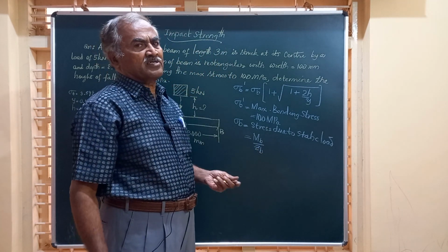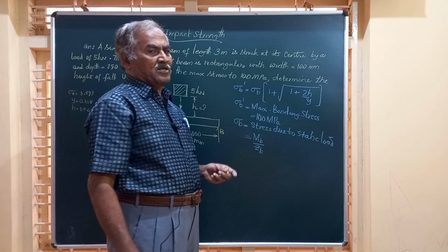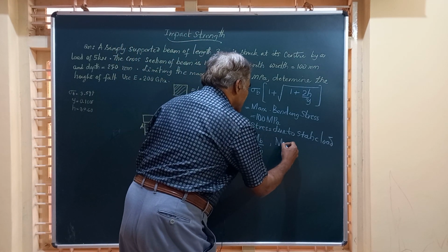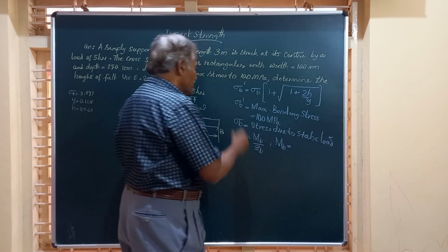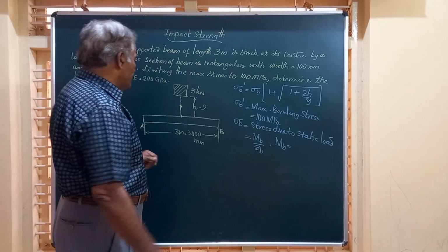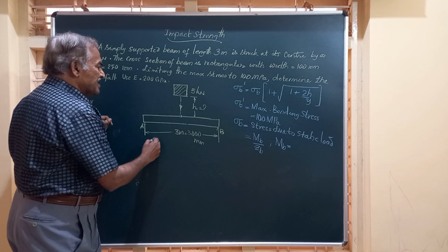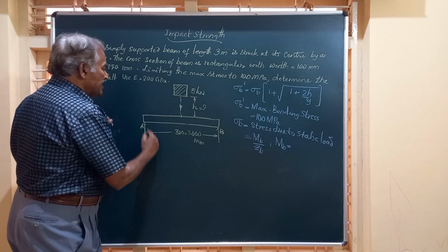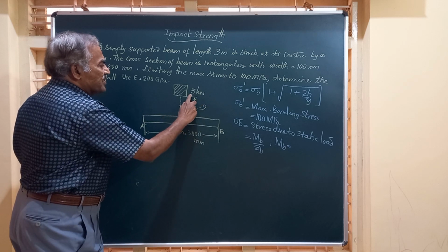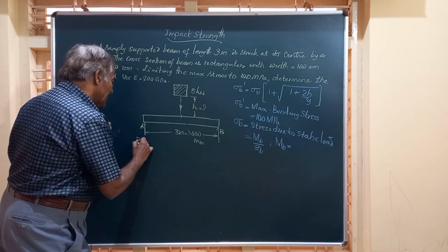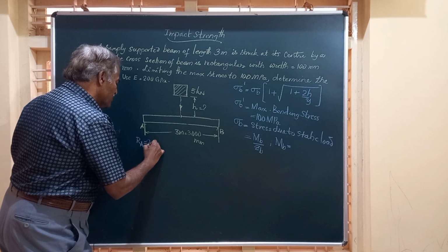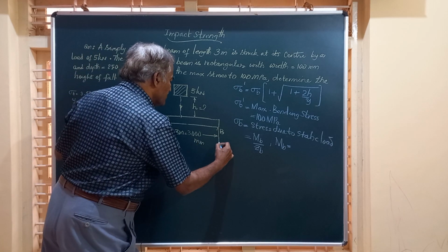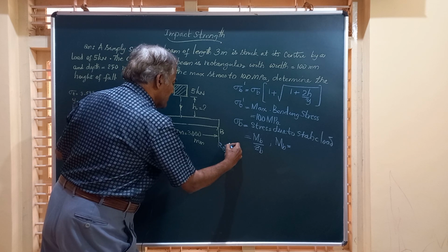These fundamentals every one of you should know thoroughly. What is the bending moment then? This bending moment is caused due to this load. How do you find out the bending moment? See here, when this load is kept here for a static case, the reaction at both ends will be 2.5 kilonewton each. So RA is equal to 2.5 kilonewton, and RB is also equal to 2.5 kilonewton.